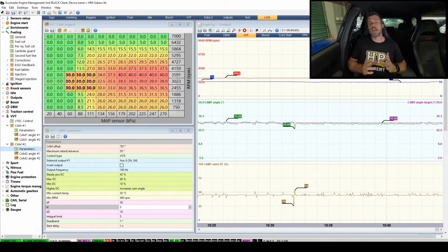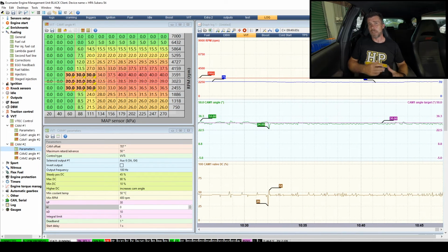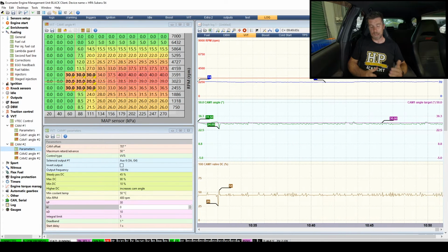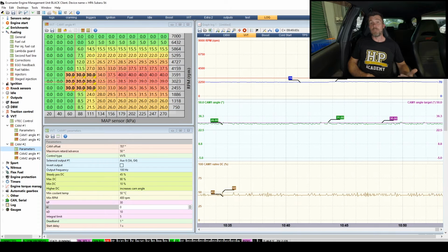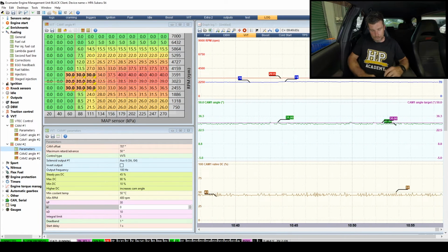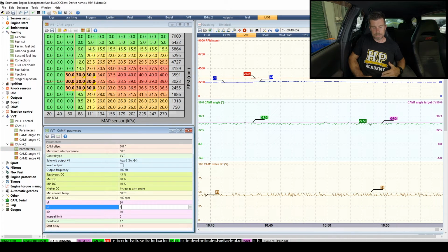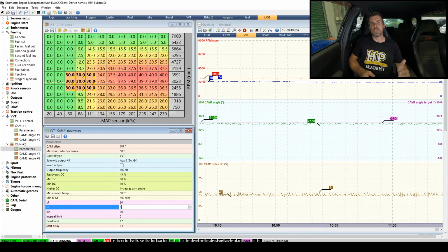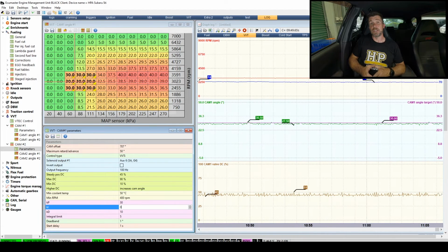Alright, let's get our time graph back up and running here. At this point we've got our proportional and our derivative gains pretty well dialed in, and we're getting pretty good control even without any integral element. However, we're going to have a look at that integral element now, remembering that's going to help remove that remaining error. At the moment we've got that value sitting at 0.